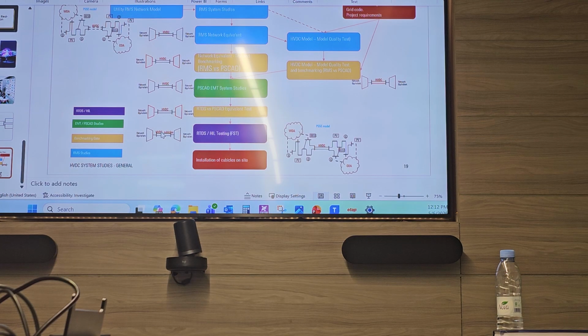So if you have normal inertia generation and something happens, then you will have a change in frequency and in power, which is delta P to delta T. It will take some time. Electronic devices can immediately react within 2-3 millisecond time, which is quite fast.